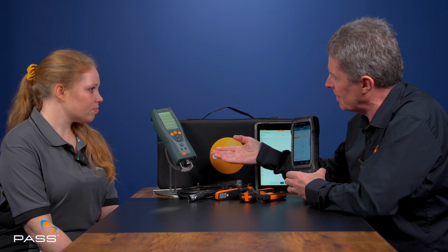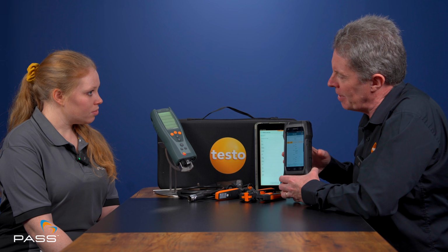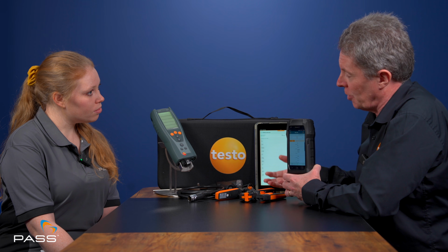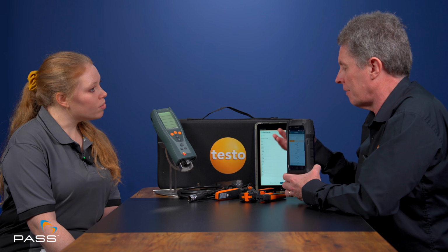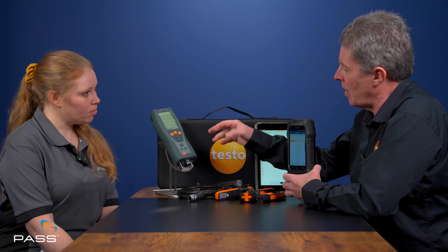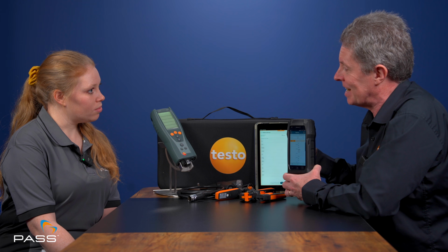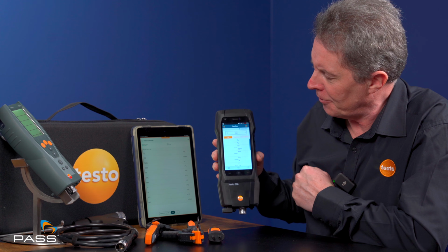With the 327, if you want to go into the menu to do the other tests, so we were saying, as well as doing the flue gas combustion readings, it can do your tightness and net by testing or your flow and return temperature. With that, you have to go in, not into a menu, but you basically go back a step and request the test you want to perform. With the 300, much simpler.